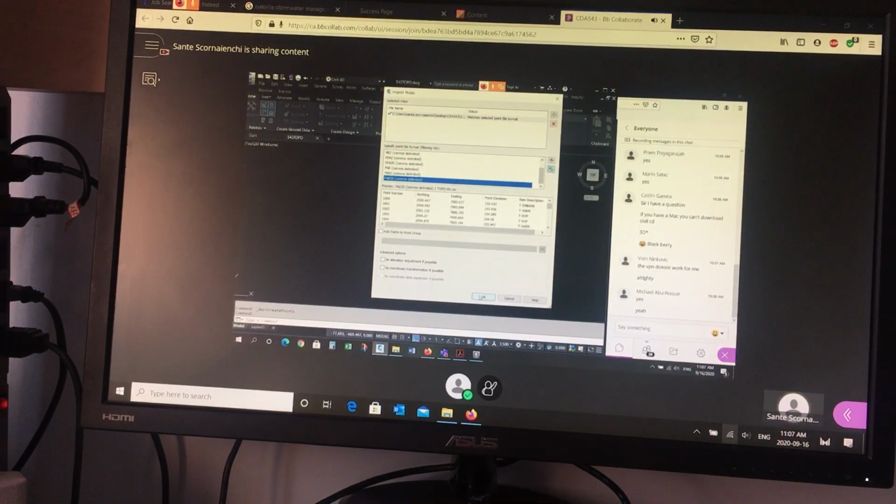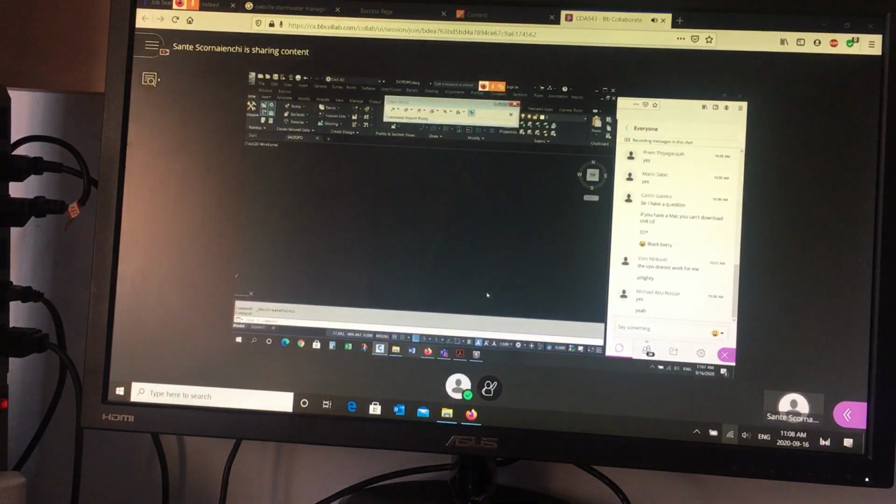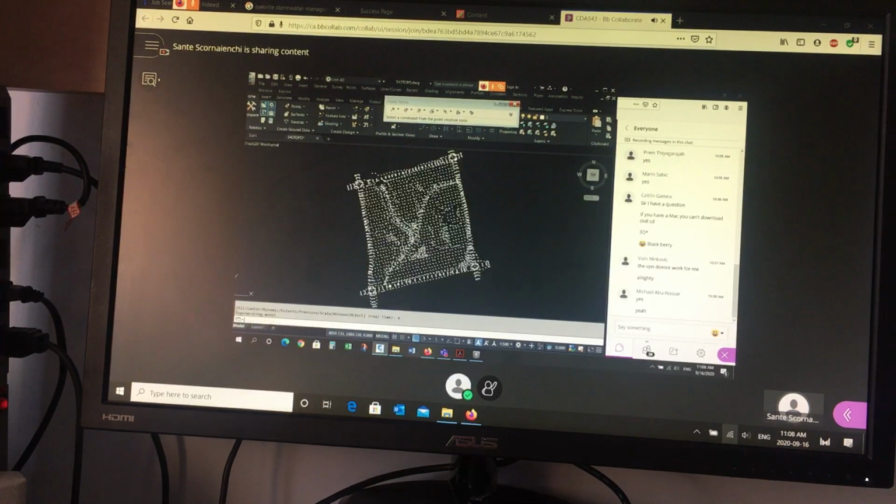Please do not do this. It's not ready to happen, but I want to show you what you get if you don't spend some time to manage your drawing. So I'm going to bring it in. Once it comes in, you probably won't see anything. Okay, so it's done. Now you don't see anything. Z, enter, E for extents, enter, and it'll zoom to everything drawn.